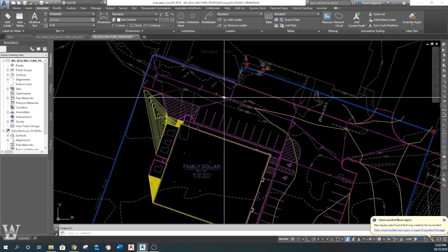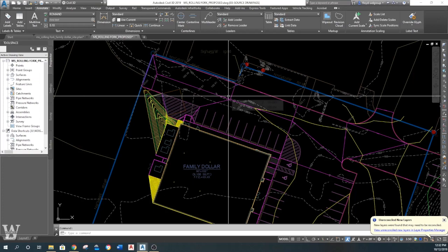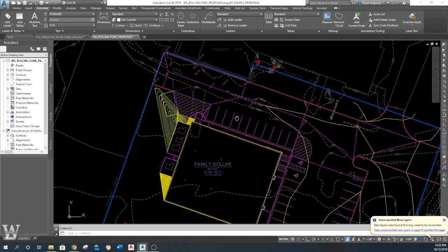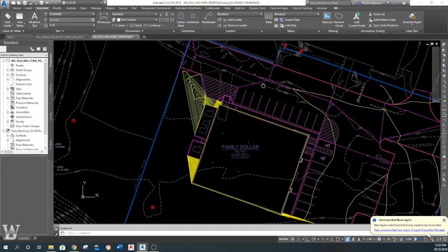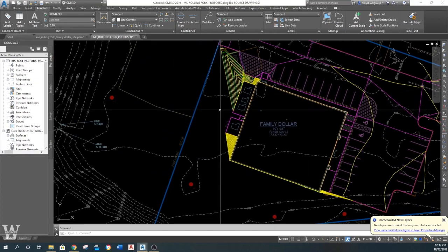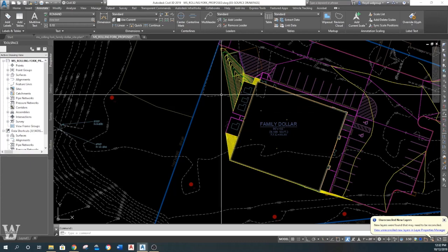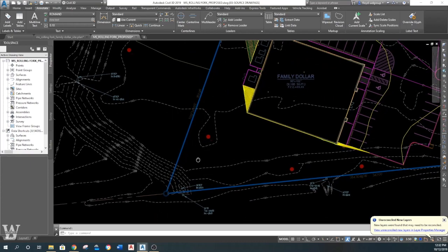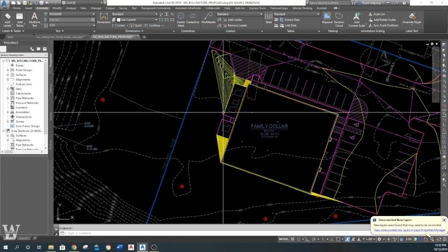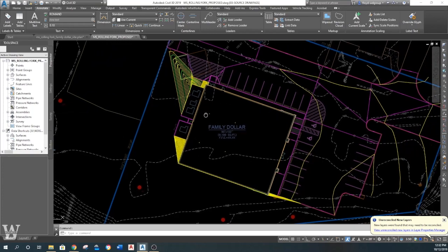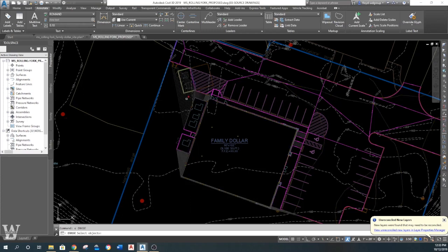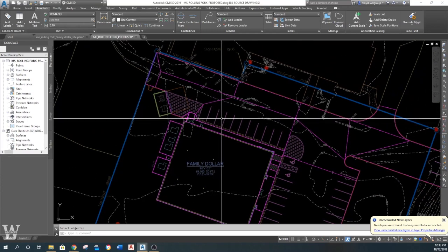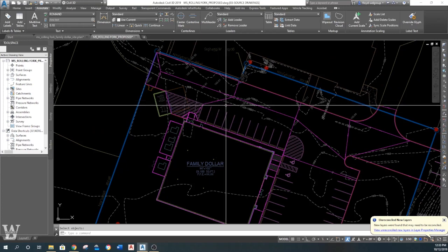And I think I'm just going to break down, put an inlet in here, and see what I can do. Because that inlet's going to be at about 103, grades 103. I can put 2 foot of cover and be about 100. I've got plenty of area to get out. I just don't want a big old huge pond in the back, but I'm going to have something like that. I reckon that's what I'm going to have to do. So I'm going to erase this test surface I had. I don't need it right now. And I'm going to go back in here.